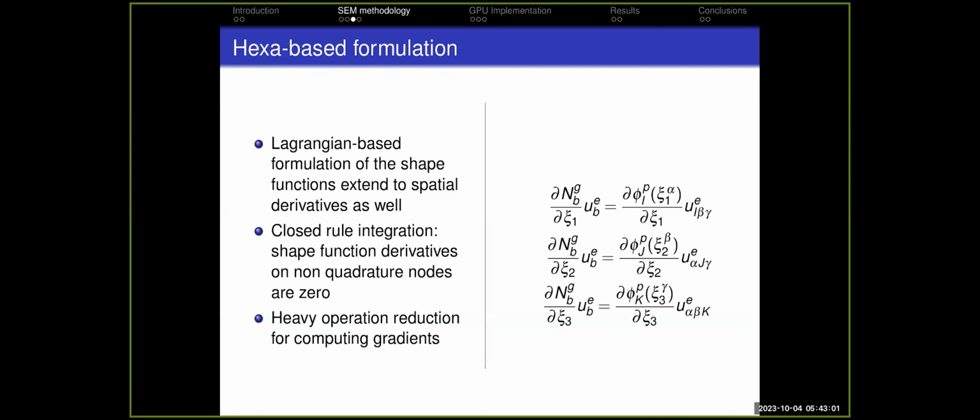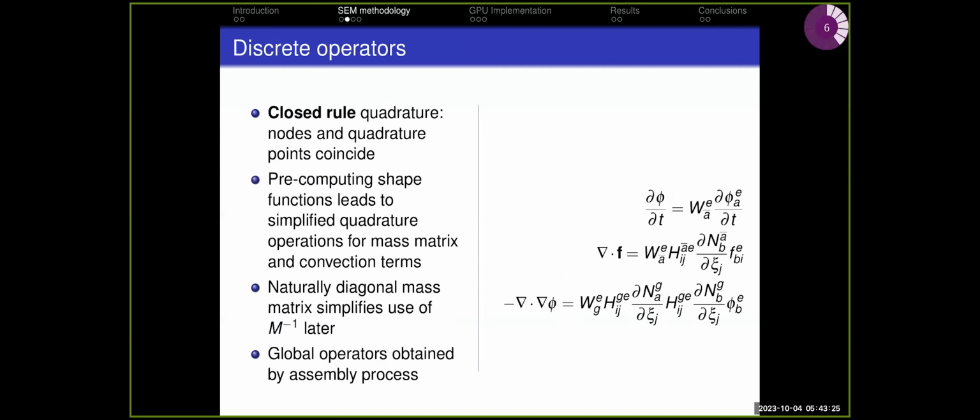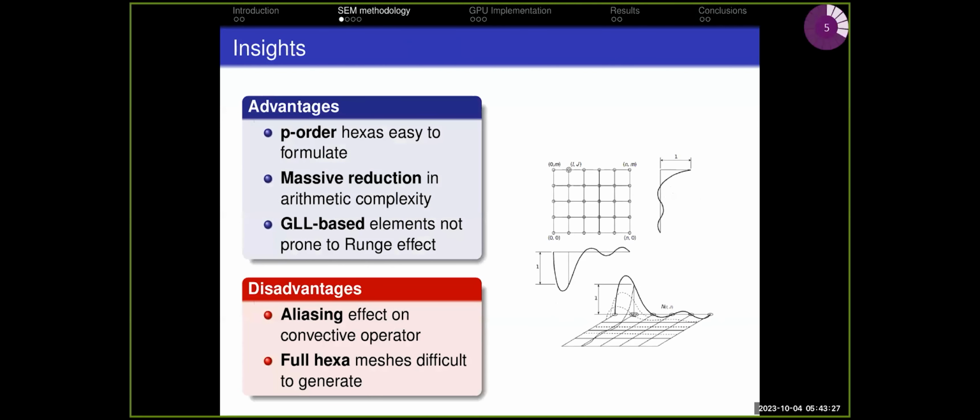So you will notice on the right-hand side here that each one of these variable gradients, especially the shape function gradients, instead of looping over each node of the element per Gauss point, are only looping over the i, j and k indexes. So remembering the figure of the Lagrangian element with the ijk indexes, this is what I'm talking about.